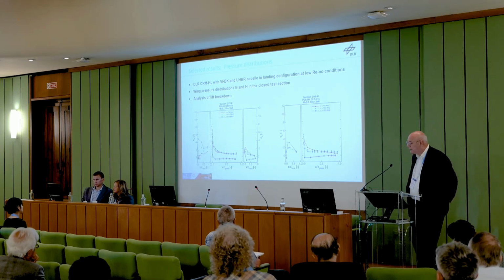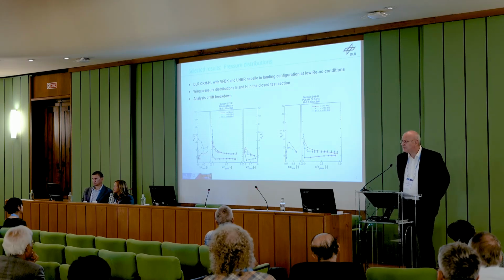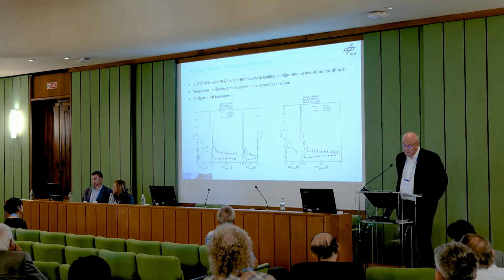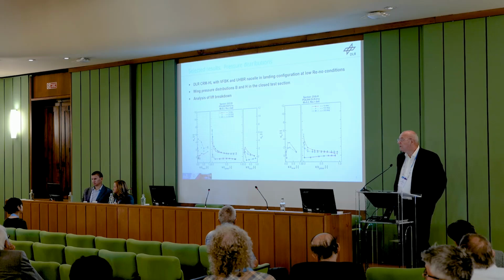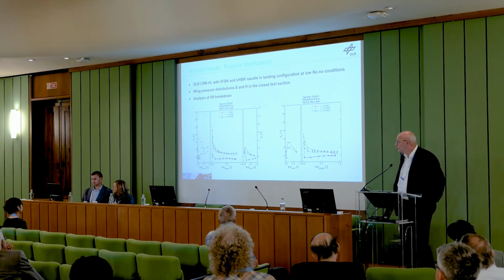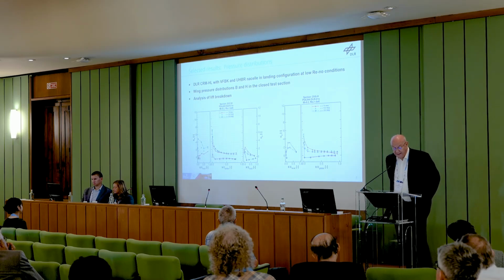Again, just a flavor. One example, we see 2 pressure sections of the DLR configuration here. The first one is section B. It's the inboard section, 3 elements. And the second one on the right is the outboard section H, which only has 2 elements, as the flap has already ended there.